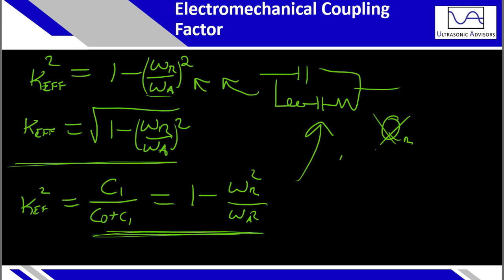So for example, from your resonant frequency, you can extract capacitance, you can extract the resistance, R1. From your resonant frequency as well, you can determine LC. So the combination of L1 times C1.